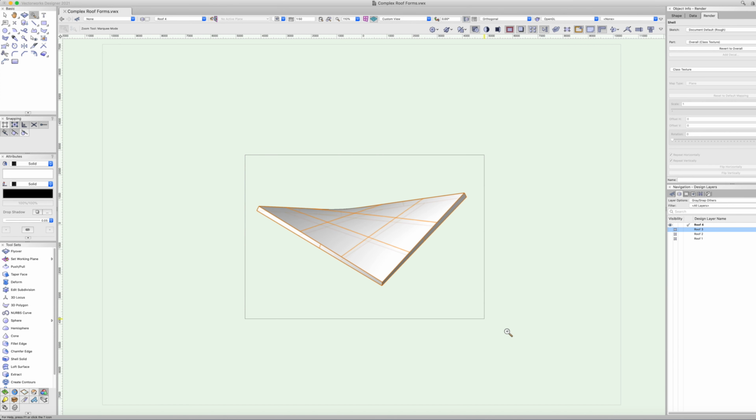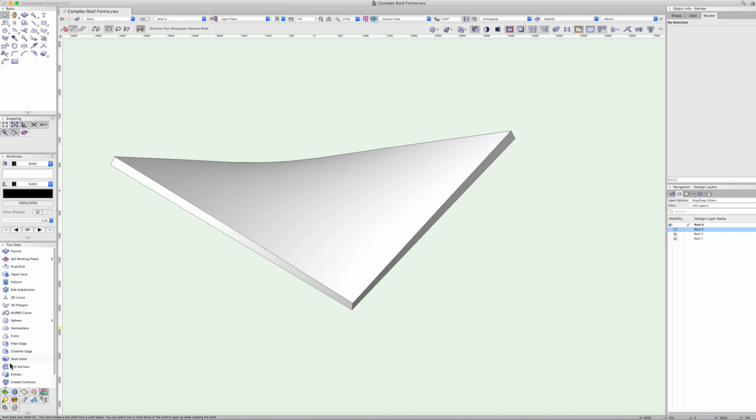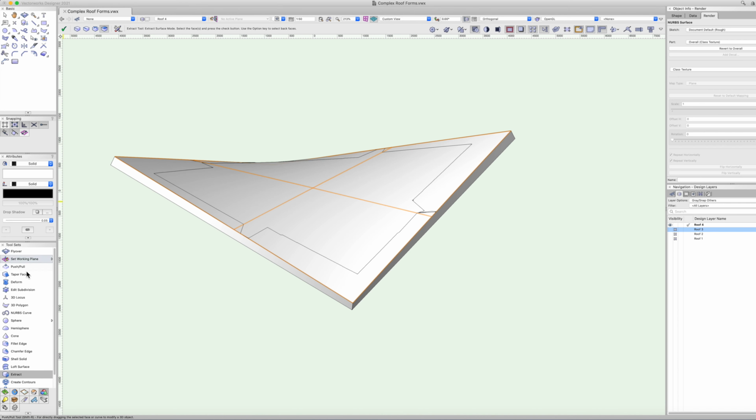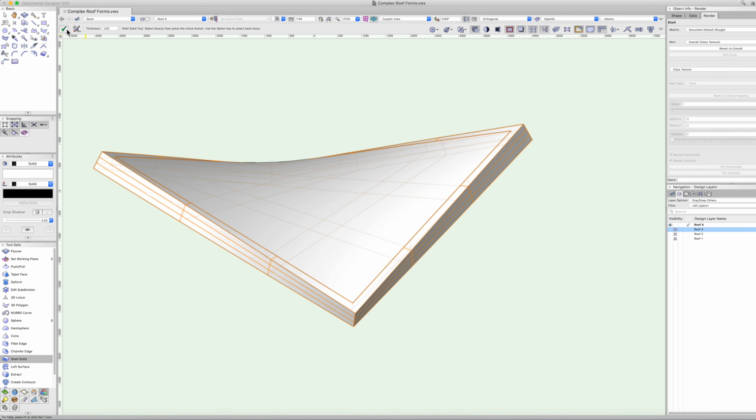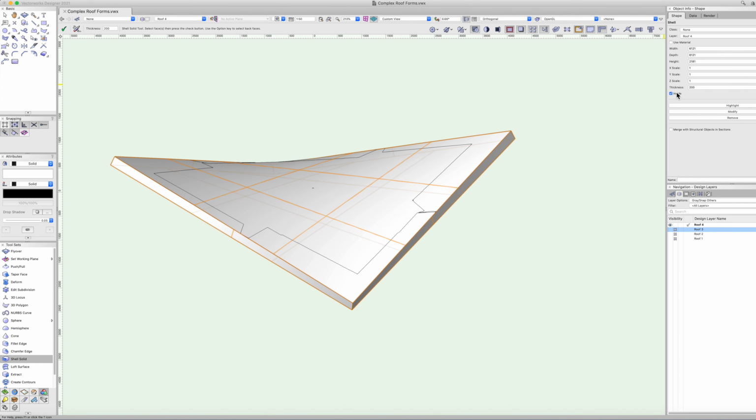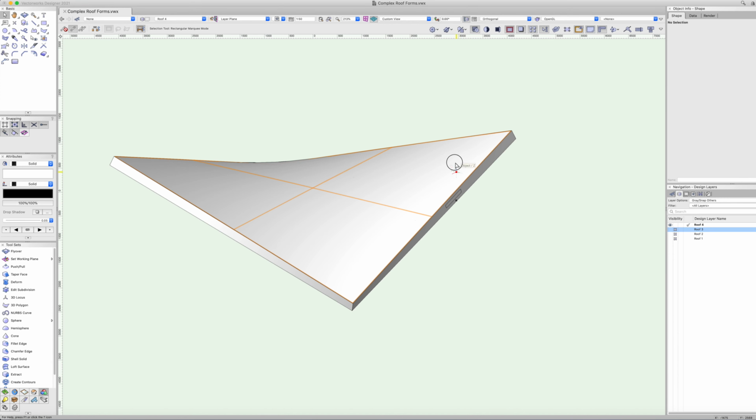Okay, so with this particular one, I think what I want to do is have 2 different surfaces. So I'm going to click on the top surface and just extract another NURBS curve rather. And then I'm just going to once again give it a bit of a shell thickness. That's a bit too much, so I can go to Object Info. I could just adjust that shell thickness to say 10 mil. Now that gives me a really nice skin essentially. You can see when I drag off.